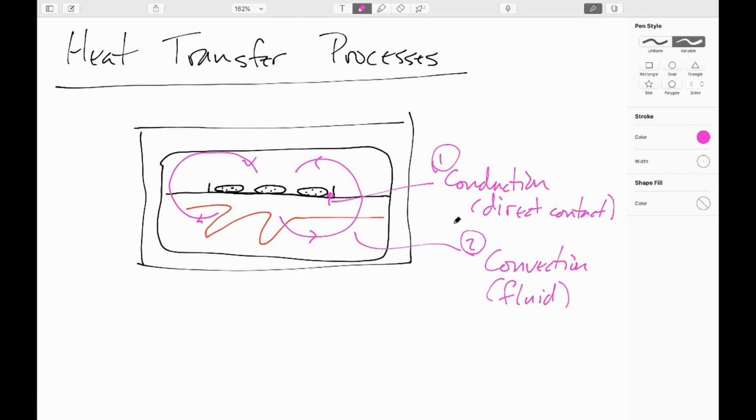Now, something that you can't ignore, but it is the least efficient channel, is, as we'll see later on, everything that has a temperature will radiate light just because it's hot. This light gets called black body radiation. And so this is why your calrod is glowing a dull red. It's actually really bright in the infrared, but a little bit of it tails into the visible, and so we're seeing that tail of the spectrum in the dull red.